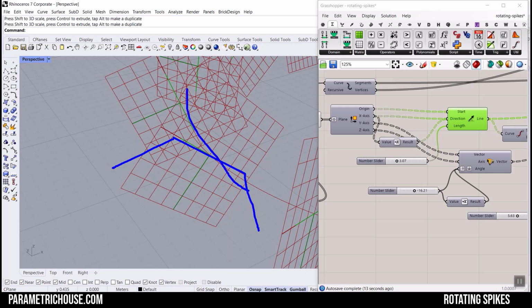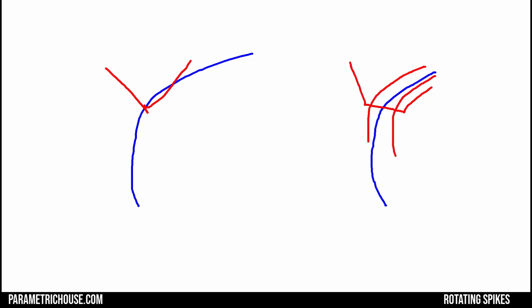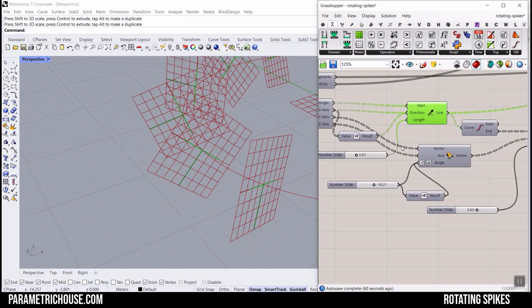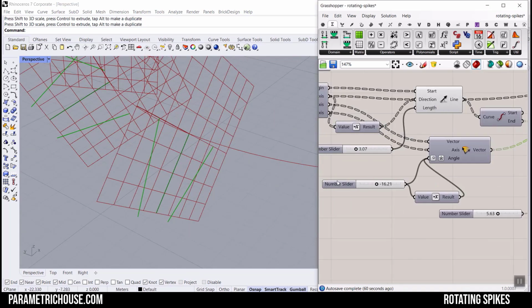The reason I'm doing this is that when we want to make this a unified mesh, we have to have some space between this. For example, let me just show you here. If we have two sets of curves and we make a pattern like this here, and instead we make it like this, what happens is that when it wants to make a mesh, here we'll have some problems because it can't find a direction. But with this one, giving it a little bit of a handle, it's also going to have a good space for making the base curve volume. Okay, so that's the trick we have to use. And then I'm going to explain how we will use handles like this.